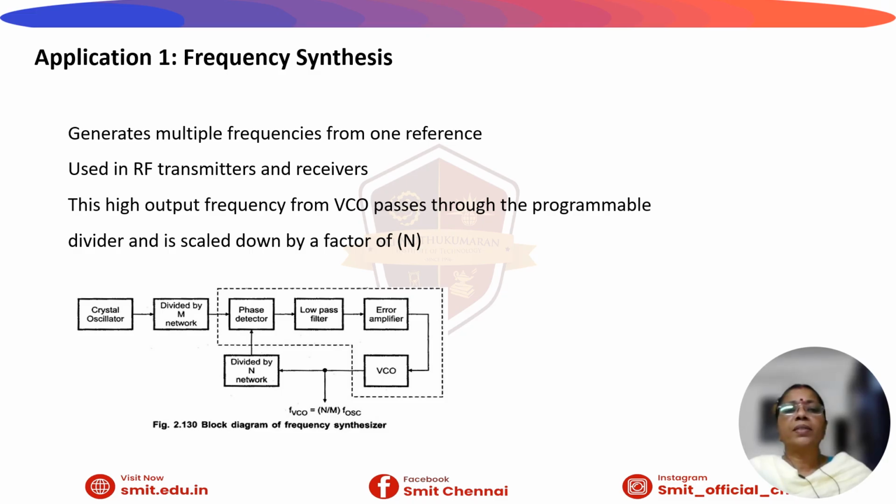Now we will discuss the application frequency synthesis. It generates a wide range of highly stable, precise frequencies from a single low frequency reference crystal. It is used extensively as local oscillators in radios, cellular phones, and test equipment. It is used in RF transmitters and receivers.